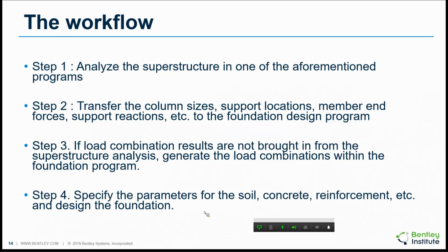Once the analysis is successfully completed, we transfer the data into the foundation design program like STAAD Foundation or RCDC or RCDC FE or RAM Concept. And if you wish, you can bring in the load combination results too, or you can generate those load combinations as we go along within the foundation design program.